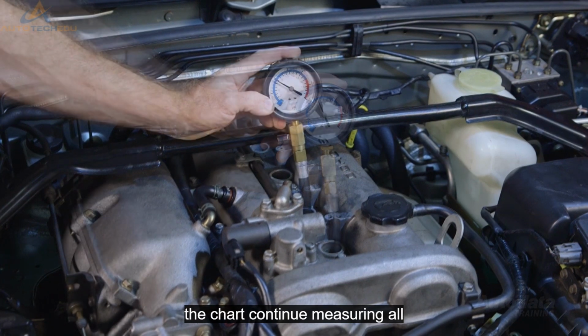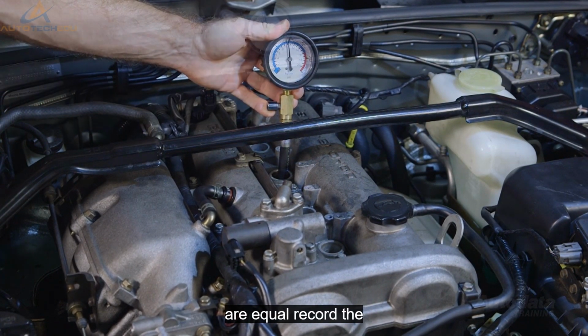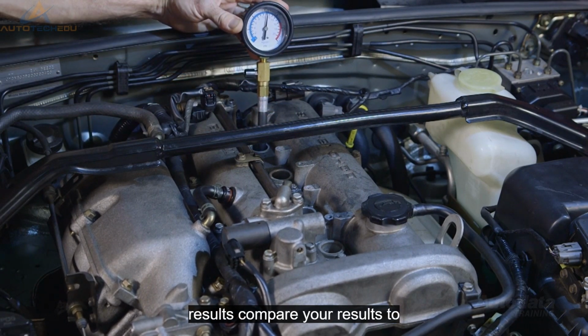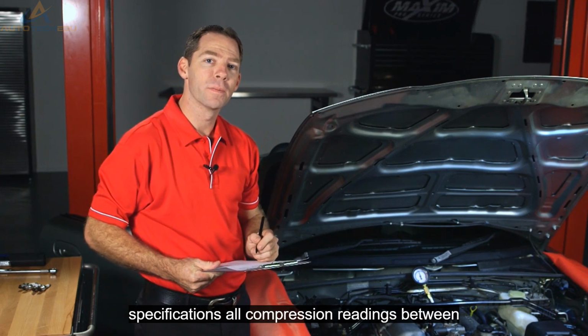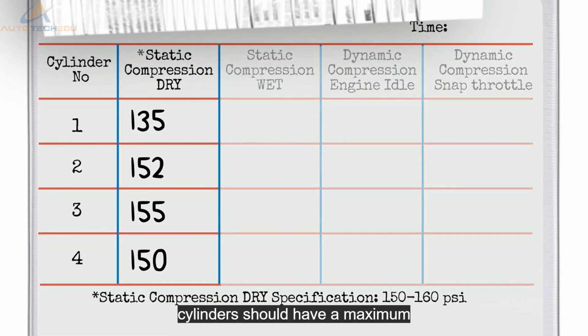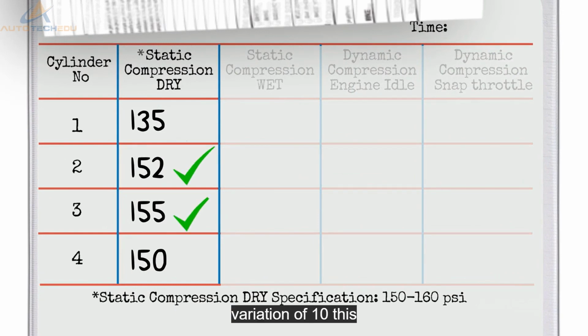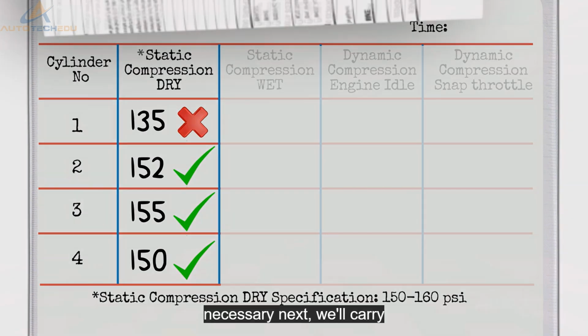Continue measuring all of the cylinders, ensuring the number of revolutions per cylinder are equal. Record the results. Compare your results to specifications. All compression readings between cylinders should have a maximum variation of 10%. This is allowable due to age and normal engine wear. If any cylinder has a substantially lower reading compared to the others, then further testing will be necessary.